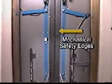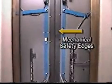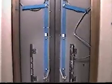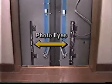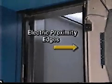Car doors have reopening devices for passenger safety. Mechanical safety edges cause the doors to reopen when activated. Photo eyes utilize light beams and a series of reflectors. If the beam is broken while the doors are closing, the doors will reopen. Electric proximity edges operate by sensing a presence in the door opening.